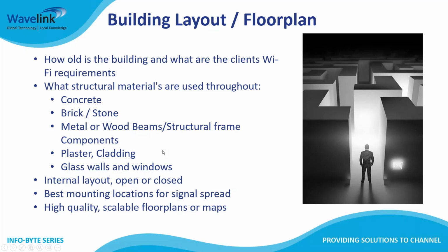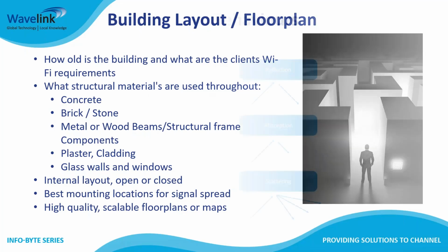Cladding materials, how absorbent or reflective are those materials? Glass, is it double glazed, triple glazed? Those themselves will stop a 4G or 5G signal coming in, so you can sure as hell bet it's going to stop your Wi-Fi as well. So really understanding all of those components can then tie back into designing Wi-Fi as efficiently as possible.